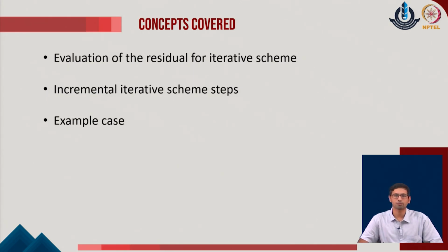So, the effective parameters on which we try to make the increments or changes appear on the external system as the loads, whereas the philosophy of the nonlinearity is introduced in the problem through increments in the stress and strain parameters of the given system. So, there has to be a good connection between the external system, which is the load and displacement system, and the internal resistance system, which is the stress and strain parameters of the given system.